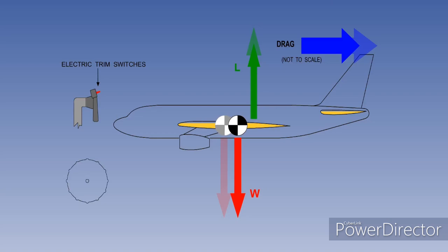Therefore, when the aircraft is being trimmed, the trim system will have an input to the artificial feel system that reduces the stick forces as appropriate. We have now reached the end of our study of flying controls. Please feel free to review the lessons as many times as you like, because they contain a lot of detail in which the examiners are interested.